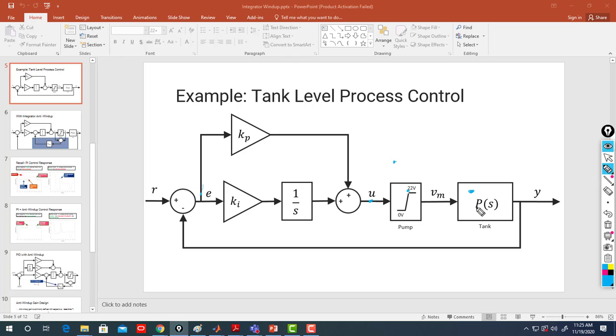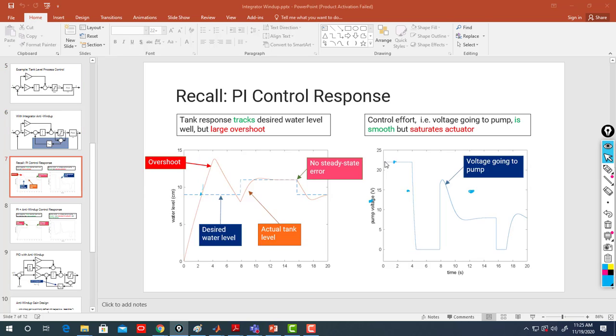Then to correct it, when the water level goes down, or when you reach the set point, the error becomes 0. If they show you the error signal, you will see here that the error becomes 0 at this point, between desired and actual water level. The error is 0 because before the saturation block the command is so much higher than the limit that the output is still saturated.